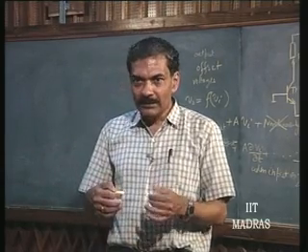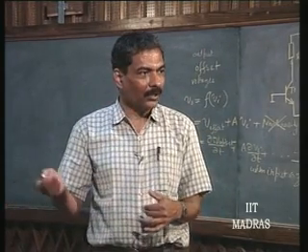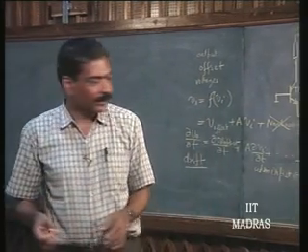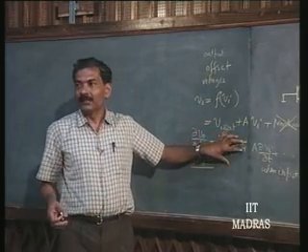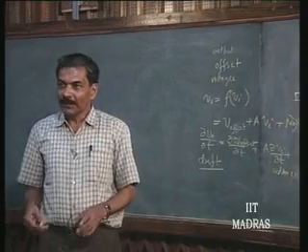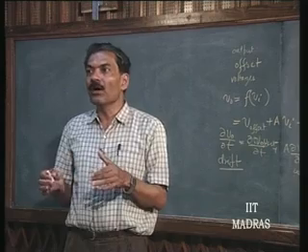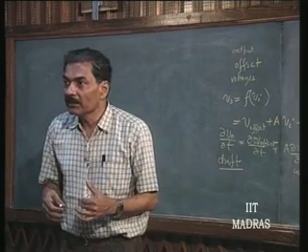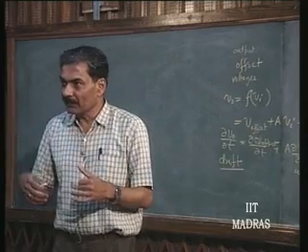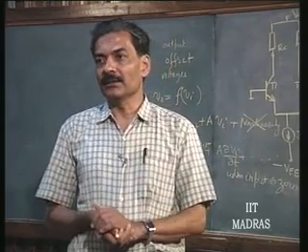But when the signal is low frequency, particularly in the case of video amplifiers or biomedical amplifiers, it becomes important that I should make this offset as small as possible. That is the reason offset is made small. What is causing you trouble is not the offset itself. What is causing you trouble is the dependence of offset voltage on temperature, time. It depends upon temperature, it depends upon operating voltage, etc., and therefore, with respect to time it keeps drifting, and that is causing us problem.